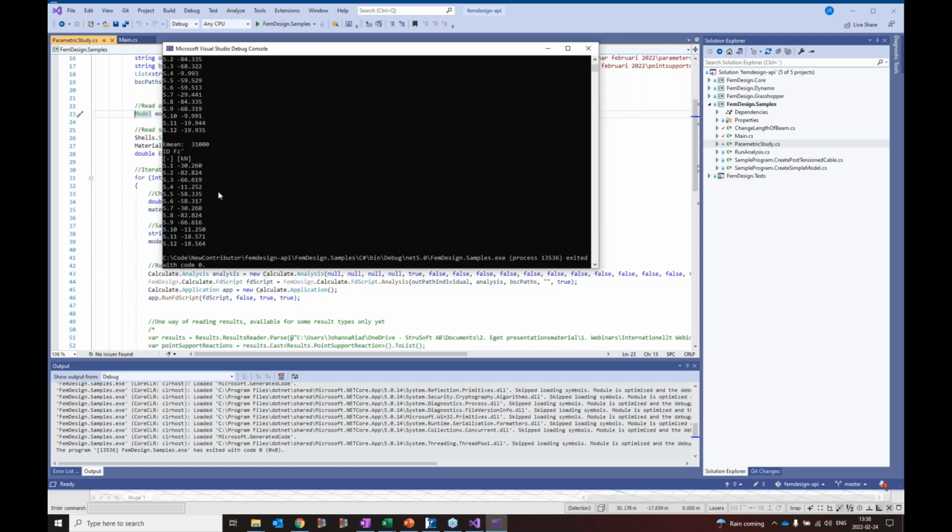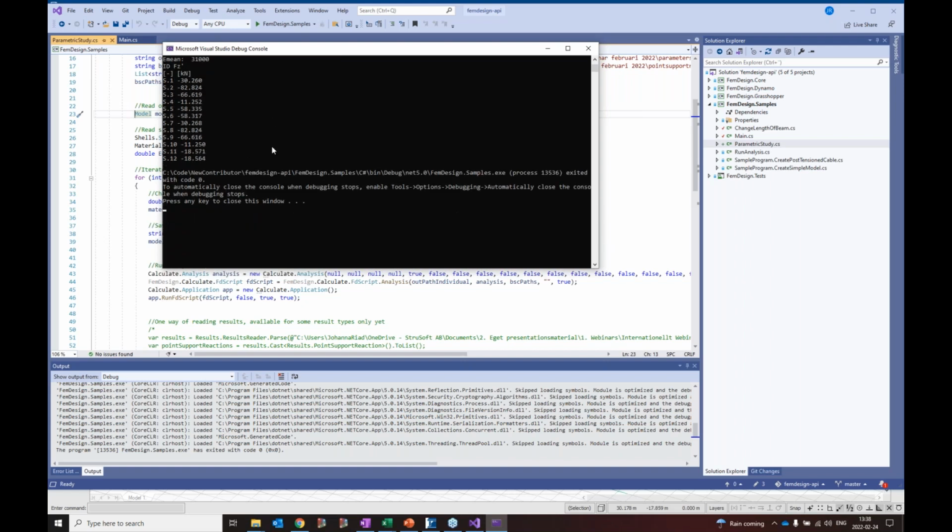So we can see that the way we set the stiffness for the plate will affect the load distributions between the columns and the walls with a few percent at least. So it could be relevant in this case. If you've got a taller building, it's definitely going to affect this more. So it could be quite useful to be able to do this check.